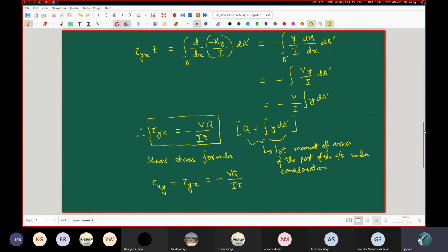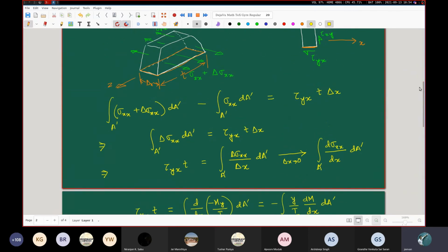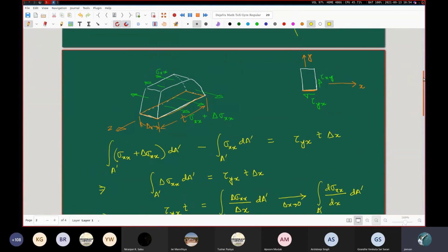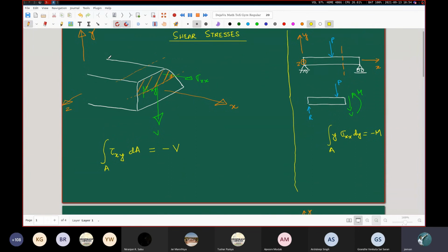So this also gives us a very important physical understanding. It is not just a mathematical convenience, it is also an important physical insight into the situation: when we are talking about the shear forces in this transverse section as a result of loadings that are taking place on this top surface, simultaneously on these horizontal planes also, there are certain shear forces being developed.